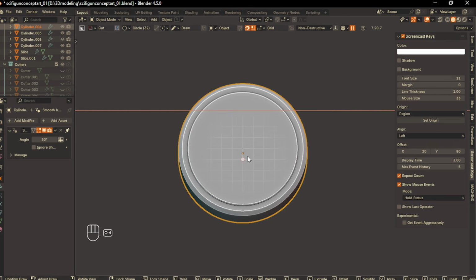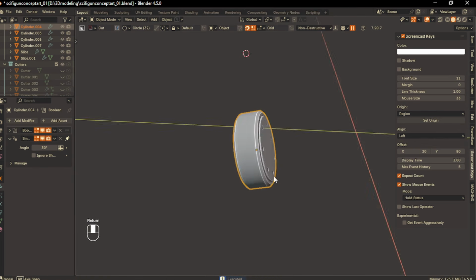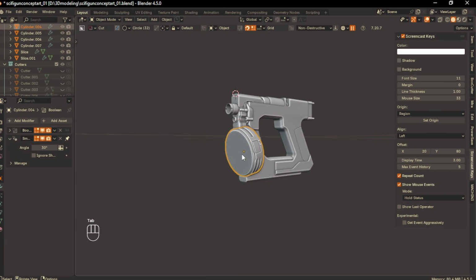I'll do a small circular cut in the middle, then extrude it inside and press V twice for a radial array and space it out nicely. Maybe 8 or 9 counts, or 6 counts looks balanced. Not too busy, just right. Now let's check the front side.